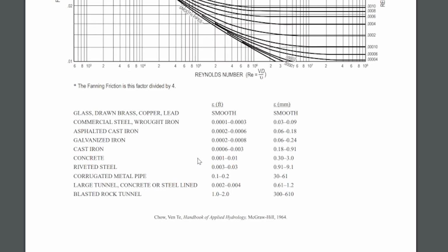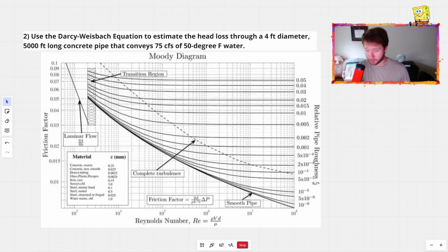And I'm just showing you here real quick. On page 201, you can find that Reynolds number equation that we used here, and our Moody chart, and also that roughness factor right here. And this is where I got that number. In hindsight, I should have used the Moody diagram from the actual reference handbook I've been using, but, you know, live and learn. So we have both of the numbers we need to find our friction factor f.